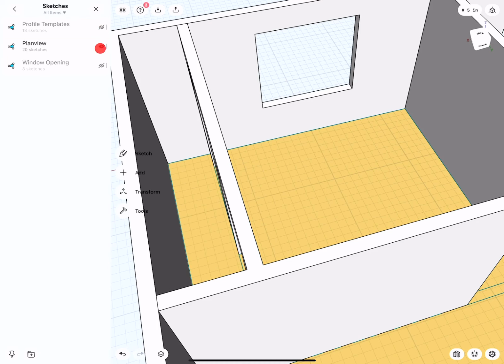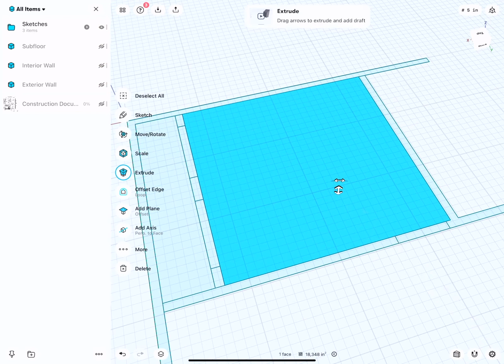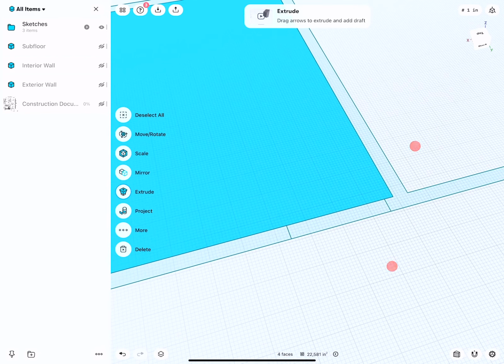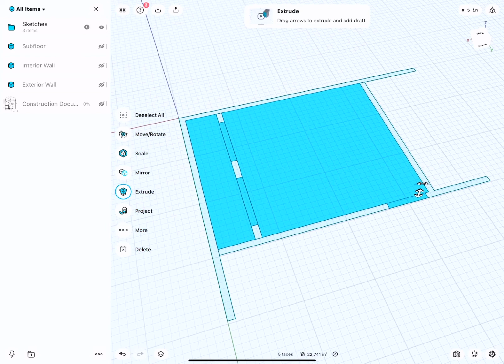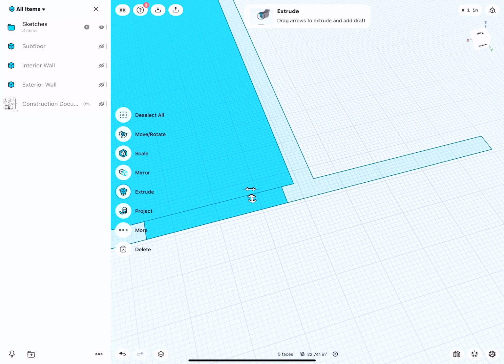So let's turn on our plan view, and all this I turn off for the moment. So here is my space for the room, inside the space in the wall where the bifold doors would be, the closet, and the door. There are two ways how to build this actually with the offset. Now inside the door actually, left and right, the wood floor is actually as wide as it is because the door frame sits on the wood floor. But inside the room, the baseboard does not sit on the wood floor.